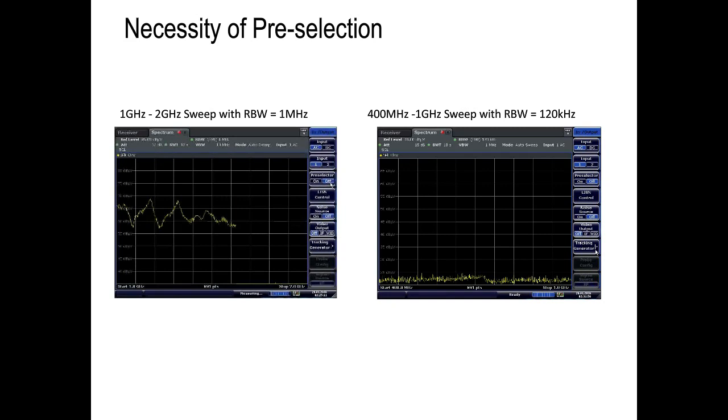Now that we know that it's a pulsed input, and we know that a pulsed input has somewhat of a sinc function response, you can clearly see that we're not getting what looks to be a sinc function response. But again, there's no overload indicator because that pulse is so short in duration, the overload indicator can't trigger on it. To be fair, you could increase the attenuation, but you wouldn't know to increase the attenuation. And if you're using measurement software, the software wouldn't know to. I'm going to copy the trace.